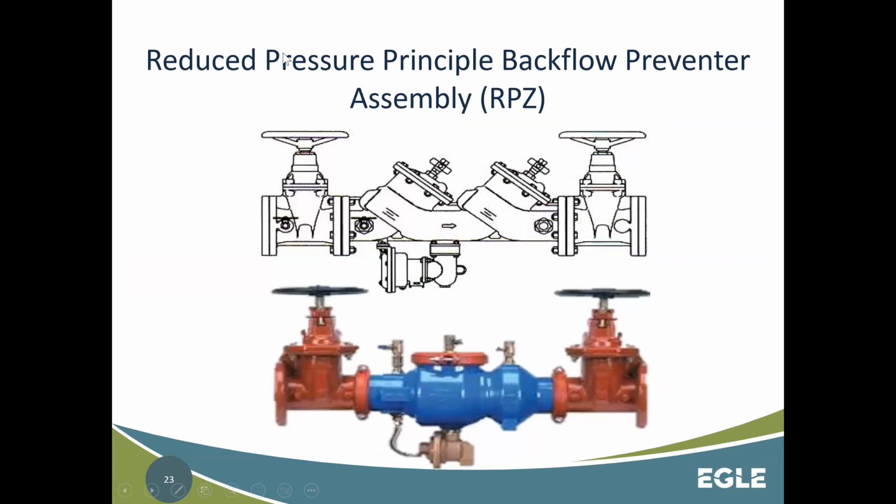So here's an RPZ, or reduced pressure principal backflow preventer assembly. Told you it's got a long name. RPZ. An RPZ is a mechanical device. The thing about it is RPZs are a little bit different than everything else. RPZ is the quote unquote gold standard for backflow preventers. And the reason it's considered the gold standard is because it protects you against everything, though it is a mechanical device. An air gap never fails because it's a physical separation.